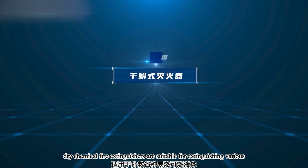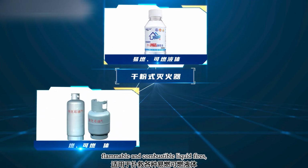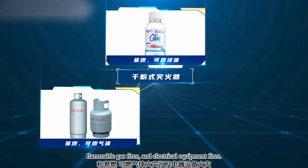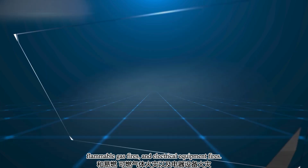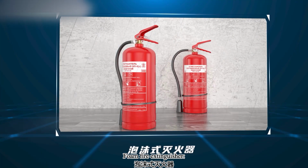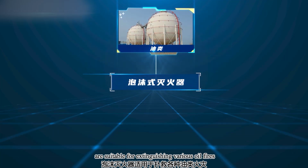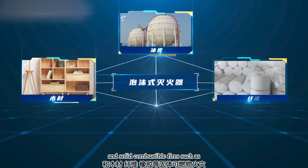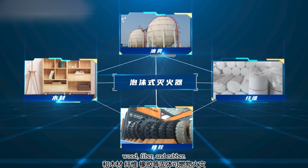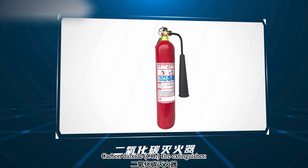Dry chemical fire extinguishers are suitable for extinguishing various flammable and combustible liquid fires, flammable gas fires, and electrical equipment fires. Foam fire extinguisher. Foam fire extinguishers are suitable for extinguishing various oil fires and solid combustible fires such as wood, fiber, and rubber. Carbon dioxide fire extinguisher.